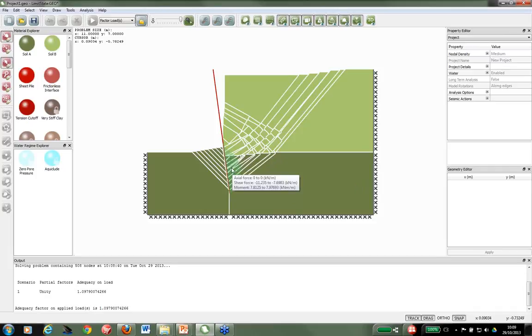So you can pick out stresses in that case, but they're only valid where the wall is collapsing with the soil. In ultimate limit state analysis, the key part of the analysis is where the collapse is going on, and these are values at the ultimate limit state, and you obviously have to remember that they may be less critical than those at serviceability limit state, but they can be extracted. So in some conventional analyses you would use these directly, and they can be extracted quite straightforwardly from the analysis.